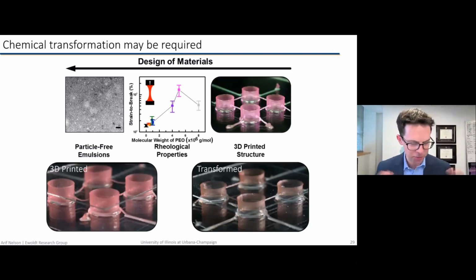These are great. There's probably something deeper lurking behind that question, maybe even a specific design objective you have that I won't be able to speak to, but it's a wide open space. Like I said, a small step beyond Newtonian explodes the range of possibilities. And you're rightly pointing out there are even other things beyond the continuum fluid properties, like how the fluid interacts with its surrounding surfaces. I'll point out, for example, with the fire suppression, you do also care about how wetting the liquid is to the surrounding materials, which is not a rheological property as such.